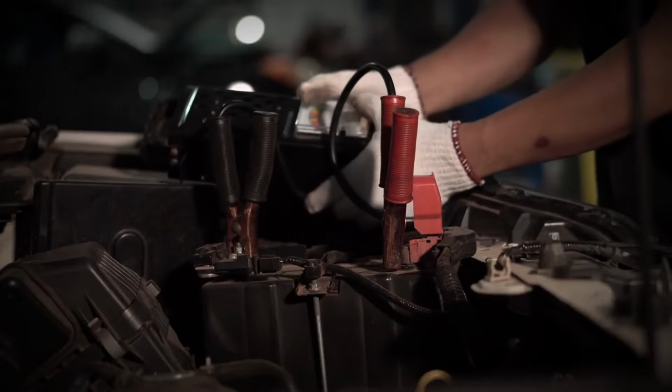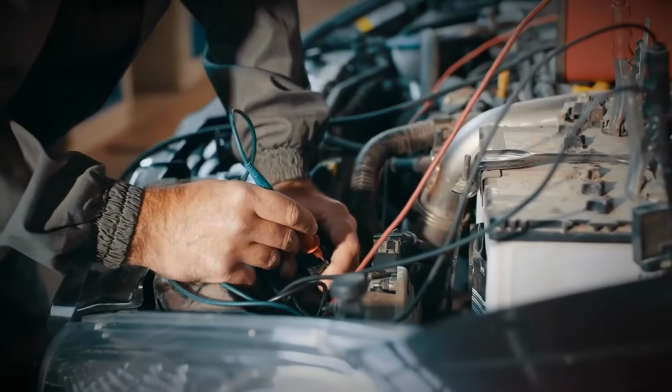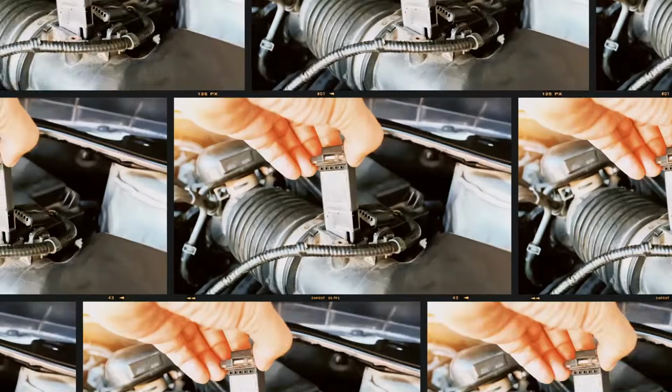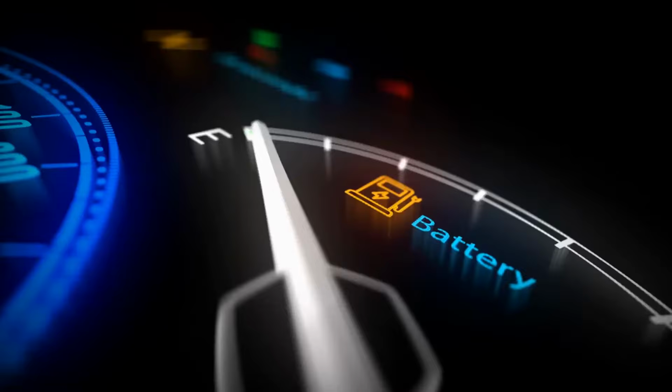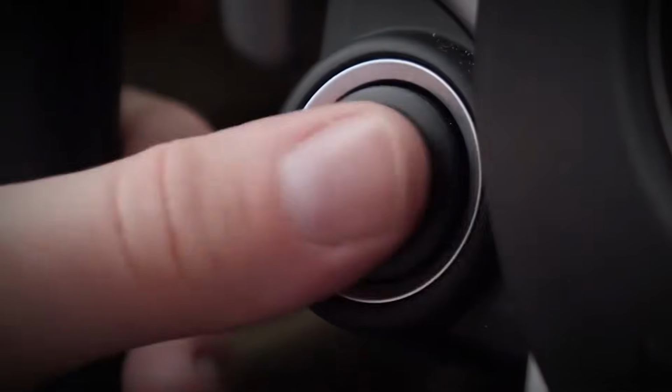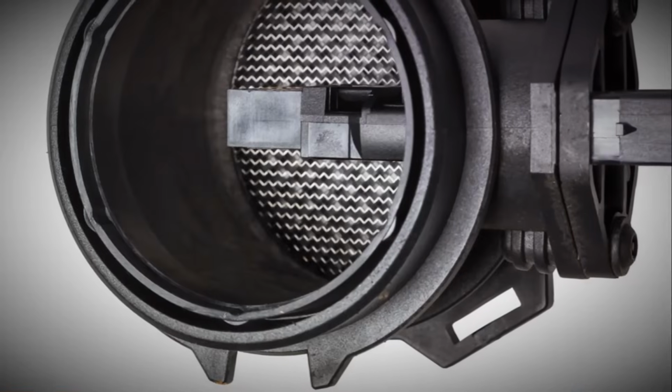Since the MAF sensor is an electronic device, it's also vulnerable to electrical problems. Over time, the internal circuitry can degrade simply due to age and heat cycles. A voltage surge, whether from a faulty alternator or jump-starting the car incorrectly, can easily damage the sensor's sensitive electronics.